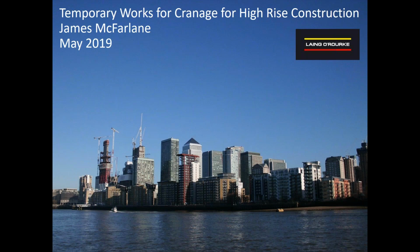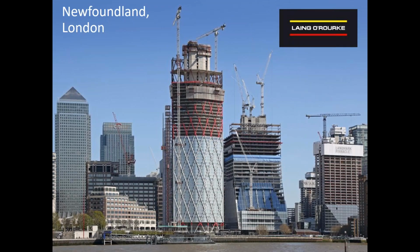This photo is about a year and a half old. It's Canary Wharf, just east of central London. The building with the cranes under construction on the left-hand side of the picture is Newfoundland, which is a 60-storey or so residential development, which is now nearing completion. This photo again is about a year or 18 months old, giving an idea about the construction methodology. You can see the jump forms of the core, the screens, and the cladding starting, which must be complete over about 20 storeys at the stage this photo was taken.